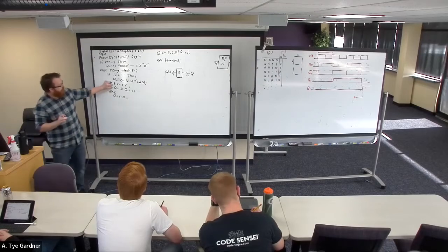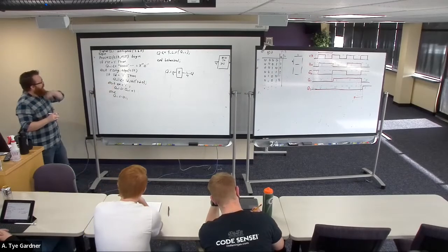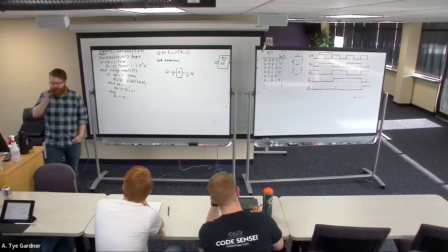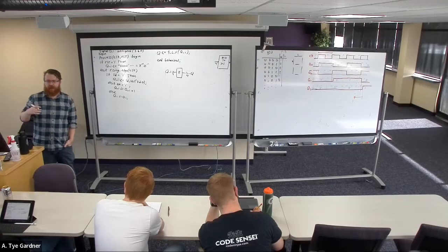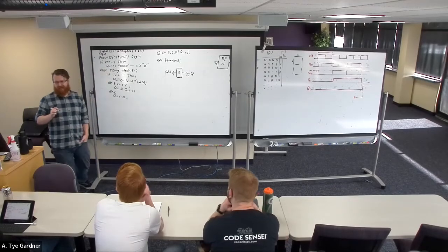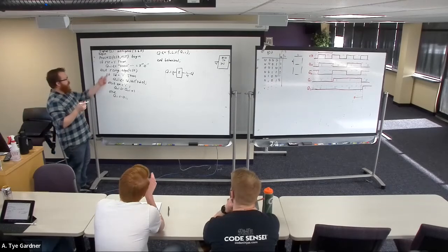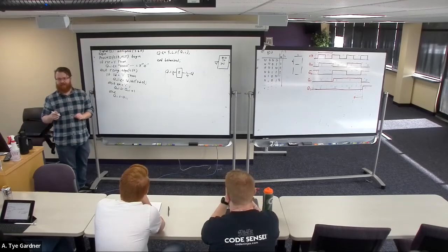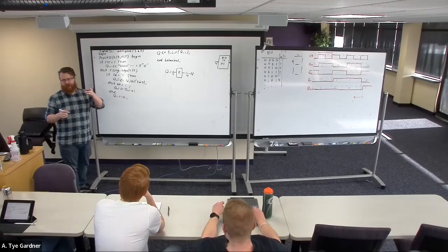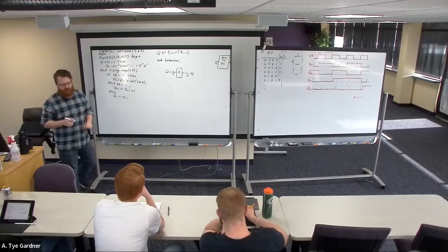So that way, right, this QI is an internal signal. And I keep doing that, which is kind of a bad habit because I keep thinking of them as internal signals because that's how I introduce them to you. If you're out in industry, the most common notation for this would actually be Q_S for signal, right? Rather than QI, because QI looks too much like QIN. So the standard tends to be QI is input, QS is internal signals, and QO is for outputs. If you go get a VHDL job.